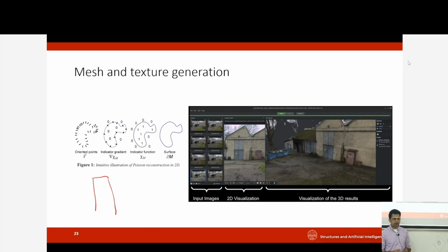If you can identify exactly which points correspond to pier cap A and pier cap B, and pier A, pier B, pier C, and so on, then you can use that point cloud information to build the element connectivity matrix.